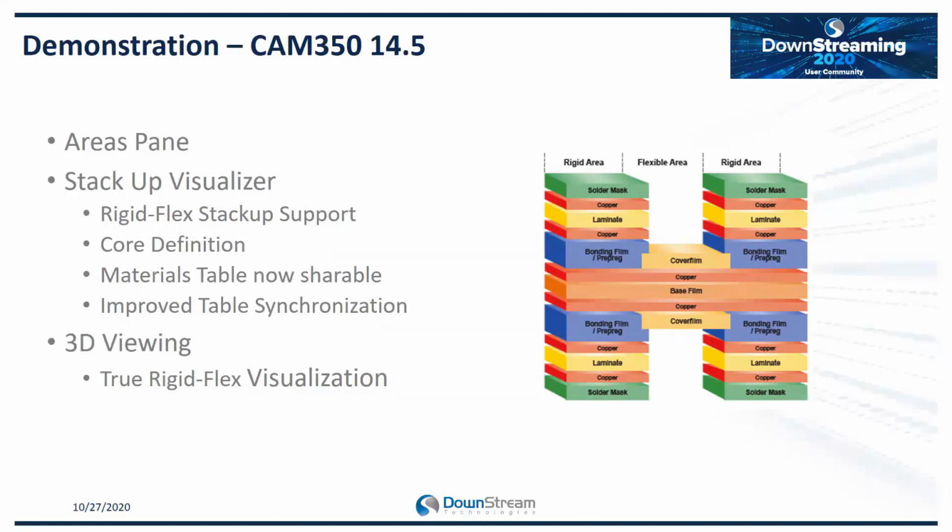So specifically ODB++. It has been our experience through this process that ODB++ out of Expedition is the most robust ODB++ that we've received to date. What do I mean by that? If you do the proper design definition in Expedition, give it proper cover layers and proper stack ups, when you pass that through ODB, it gives us really robust data that we can properly represent.